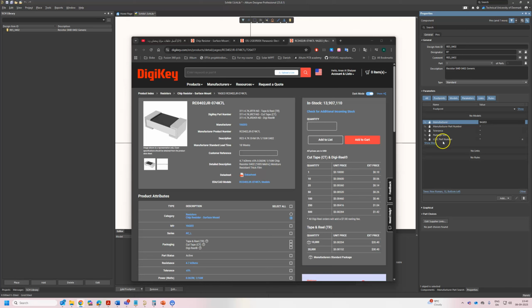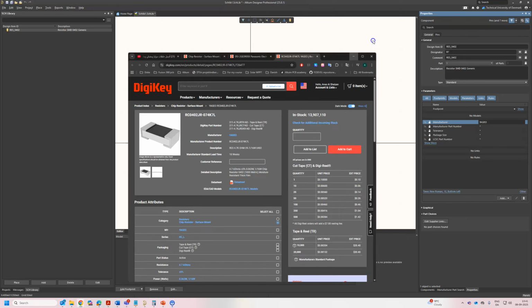So why I like to add this LCSC, because if I have a specific resistor, I will look on the LCSC website, and then I will add the LCSC number. That's because if you're ordering from JLCPCB, they're using this manufacturer, and when you upload your bill of materials file, it will automatically detect this number on the JLCPCB system. Close this.